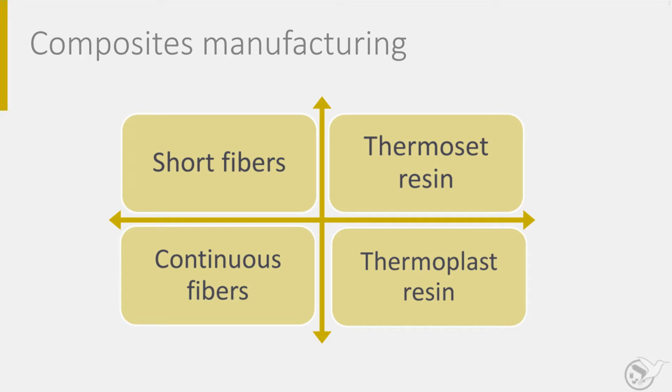Thermoset polymers are made by mixing two or more chemical substances which react and form macromolecular networks. At the start, the viscosity of the mixture is very low, but with time the mixture solidifies, and this solidification is irreversible. Thermoplastic polymers have one chemical substance with long molecules. At room temperature they are solid, and at high temperatures they become soft, though they maintain a rather high viscosity. The heating and cooling are reversible. It can be repeated multiple times.